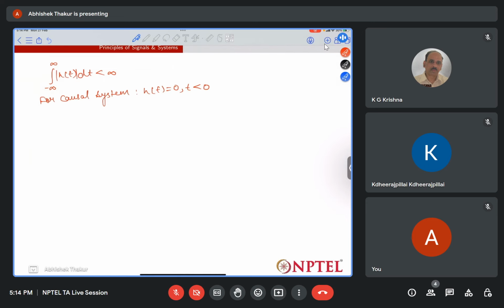And as you have already studied this week, the pole does not lie in the region of convergence. A pole can be the boundary, but the ROC does not contain poles. So poles only form the boundaries of the ROC.